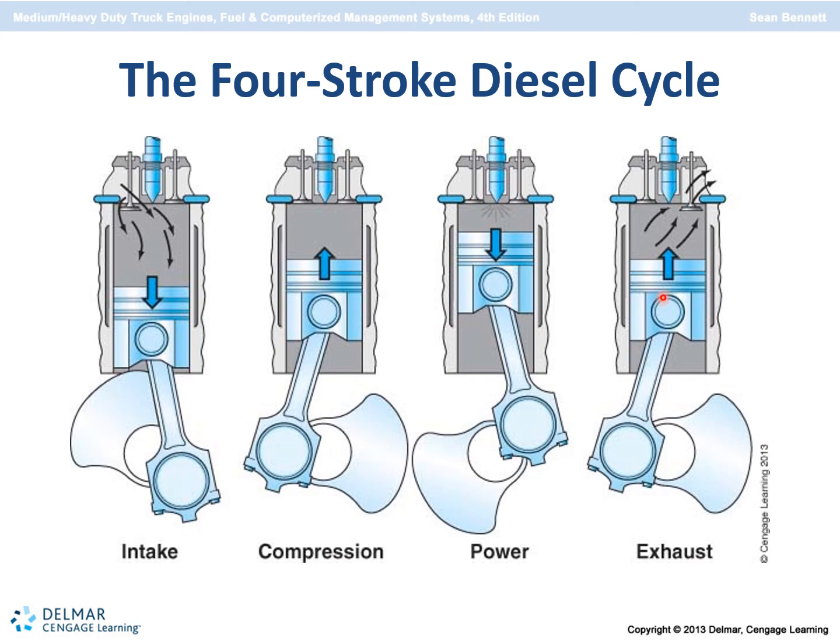On the exhaust stroke, 2 things happen here. The piston is coming up with the exhaust valve open, pushing the light, burnt, dead air out of the cylinder. Towards the end of the exhaust stroke, the intake valve will open and introduce fresh, colder, denser air to scavenge out the cylinder as the exhaust valve closes. And that is our 4-stroke diesel cycle.